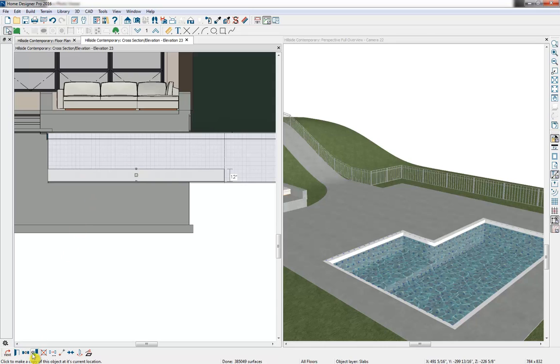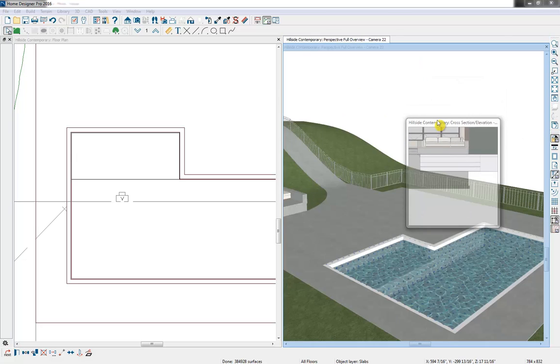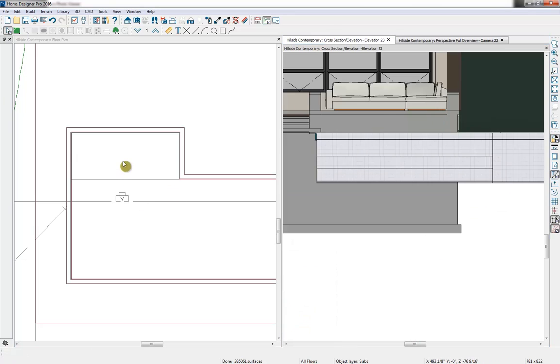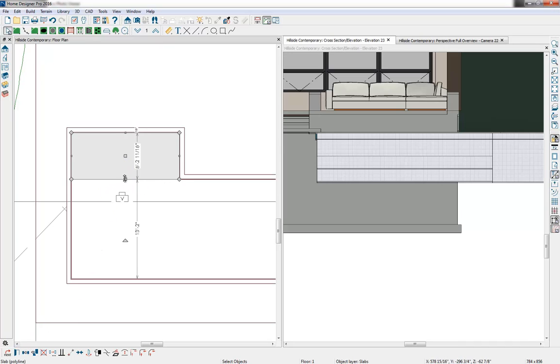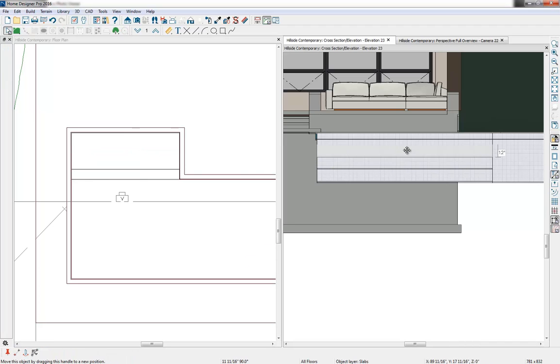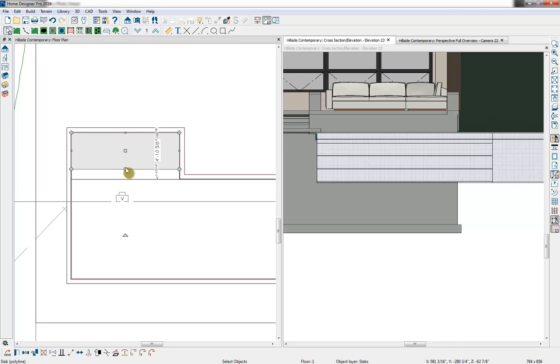And then I can just copy and paste in place, have a replica there, and then move that up. Let's have our elevation and our floor plan. So I'm going to click on that tab and bring it right over, and there we go. So now we have those two in place. I'll single click on, hopefully that top one will move it and make sure. There we go. Then we'll just copy that in place and bring that up and resize that, and we'll be all set there. So very easy to use your slab tool to create those kind of stairs in here as well.